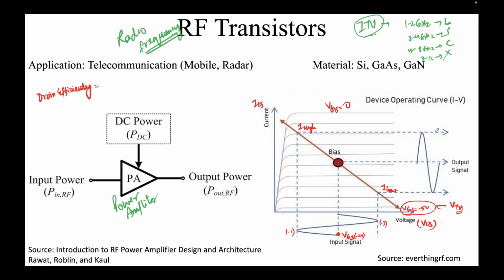Okay, you're seeing this, but where is the amplification? So essentially you put a load. Which load value to choose is a different thing. For the most efficient power to be delivered, the maximum power to be delivered, this load value magnitude should be equal to the output conductance of the transistor.